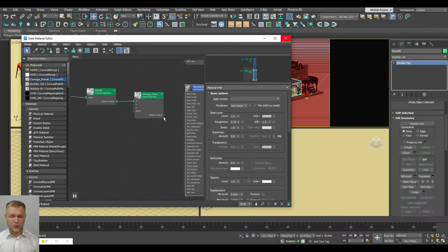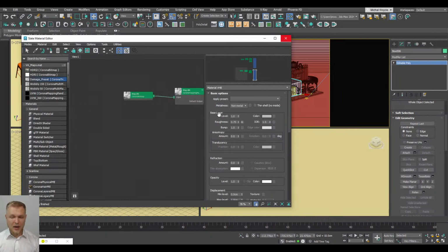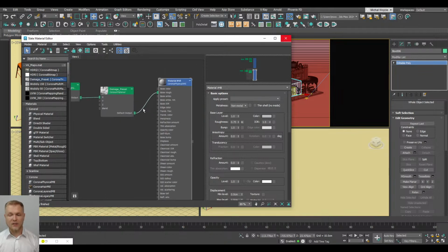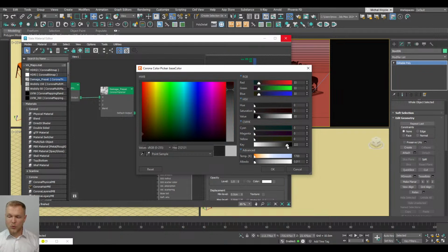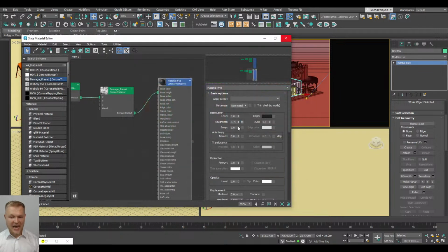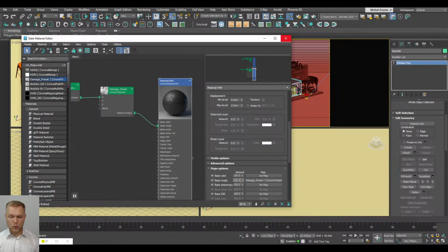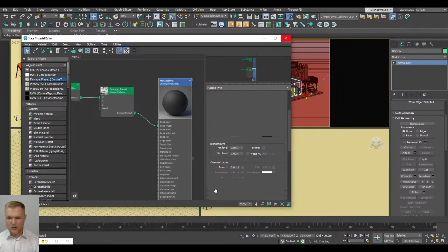So first thing I'm going to do is apply a special map that I called damage map. So this is damage preset. It's just for a little bit of roughness in our metal or non-metallic object. So let's go for non-metal because I don't need this to be metallic. Also, we're going to make this closer to blackish, not fully black, but it also shows that we're getting that effect. Because it's a little bit too much, I'm going to lower this roughness to something around 15, so the effect is very soft. So let's go for 25-ish, perfect.